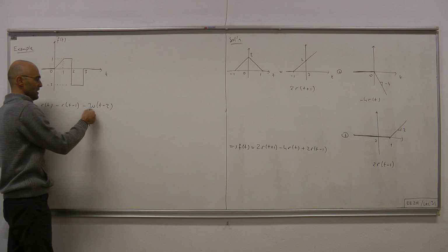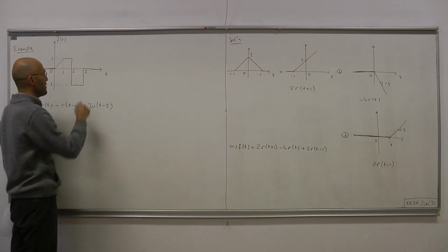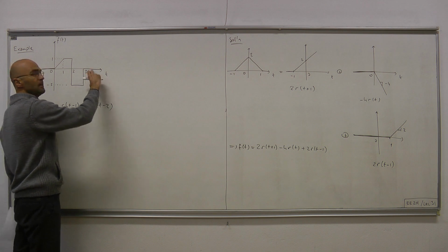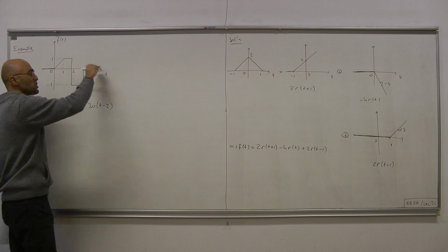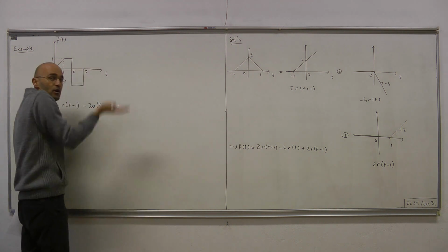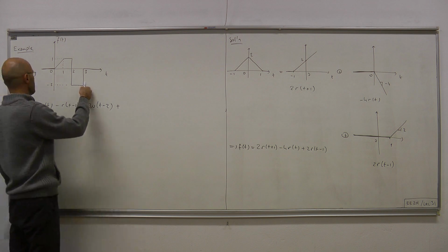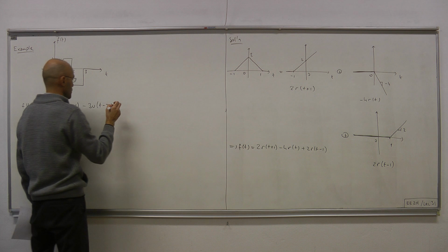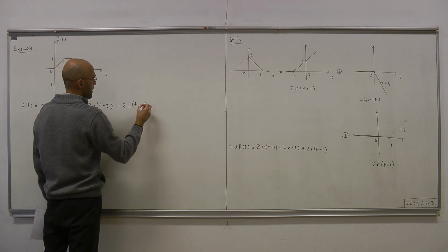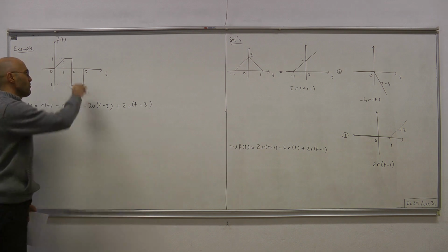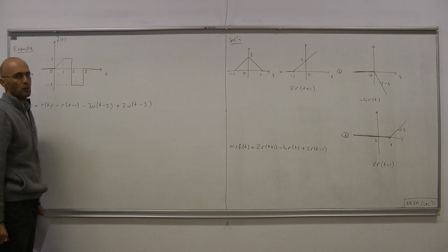Okay, and then everything is fine for a while, but at t equals 3, another change happens, and that changes the value: it raises 2 units up, and remains constant there. So that means we have to lift everything up by 2 units, starting from t equals 3. So finally we have 2u(t minus 3). And from that on, no change happens, therefore this is where we stop.